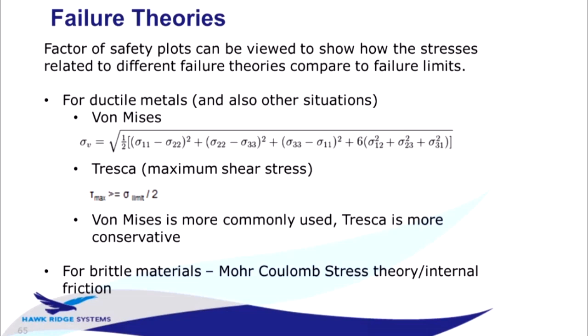But one of the key things that we want to do when we finish up a stress analysis is make some assessment of performance, or failure, of determining how close we are to failure. And we're typically going to use some sort of failure theory. The general concept of a failure theory is that when I combine all the stress information that I have, it presents me with a single number that I can go compare to a failure limit and make a design decision from that.